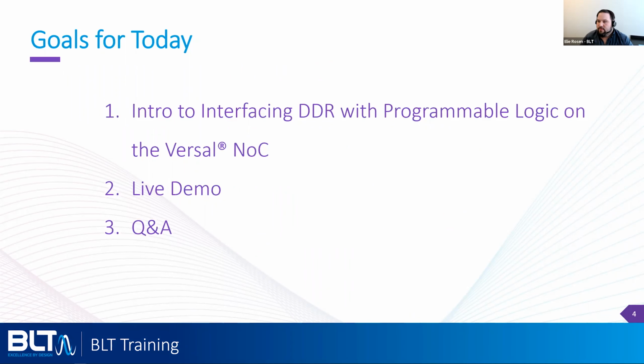So we're going to cover a few things. I want to get us all up to speed on some of the architecture around the NoC, or network on chip, and how Xilinx brings the network on chip in a dedicated fabric so that you can just pipeline your designs and move large amounts of data everywhere between these Versal devices as efficiently as possible.